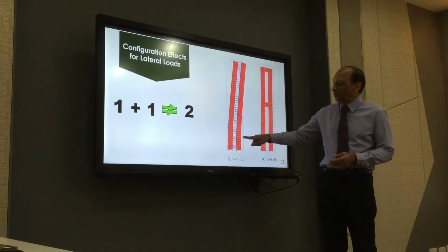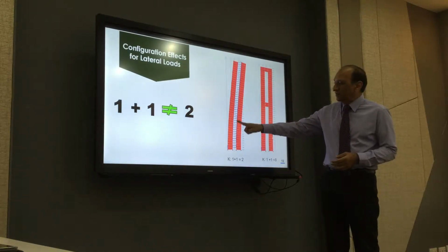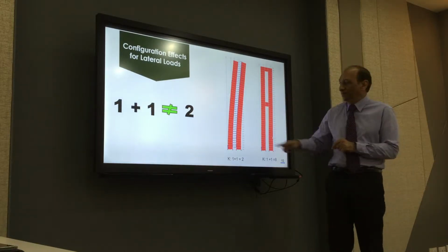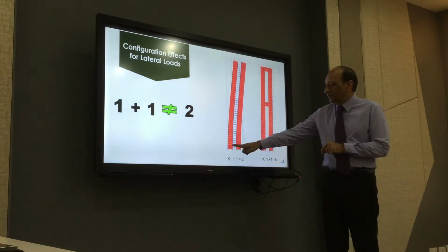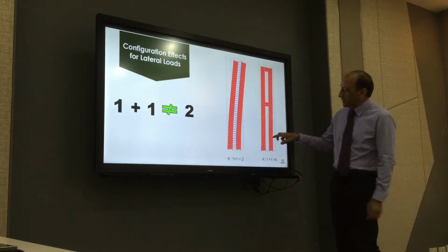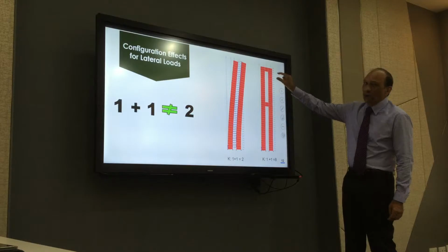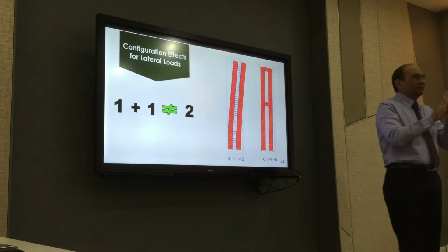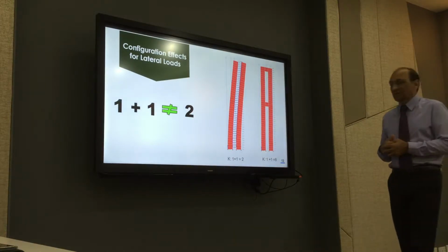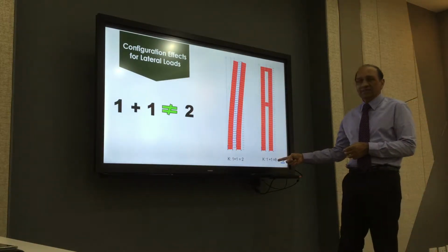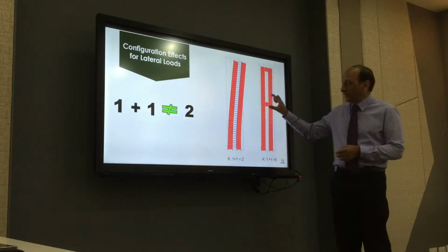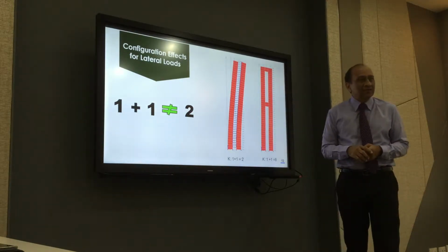For example, if you have two walls connected by a flat slab which has a very small stiffness, so basically no connection in between them, then the total stiffness will be this wall plus this wall equal to 2. However, if you take the same two walls and connect them through a proper shear transfer mechanism, then you can get a far increase in stiffness. Here in this case, 8. So 4 times more than the stiffness of the same wall by putting the connecting elements in between them.